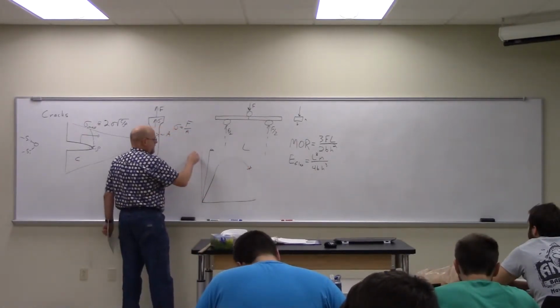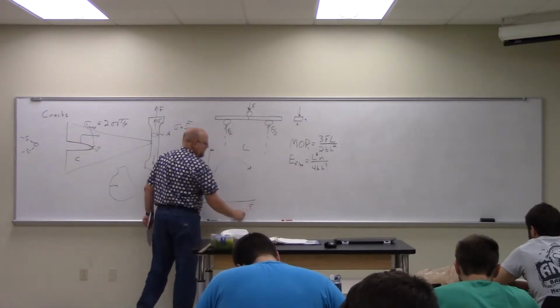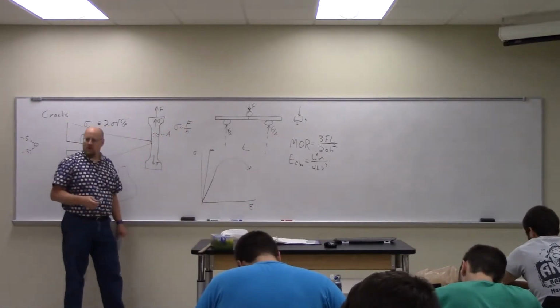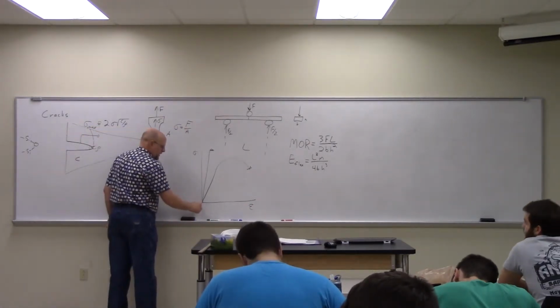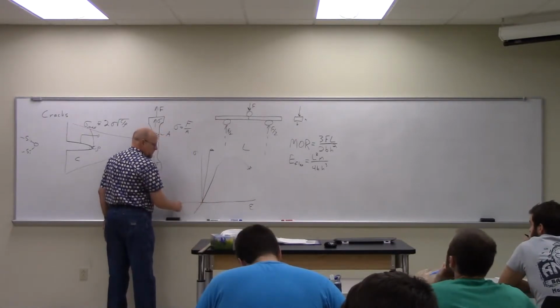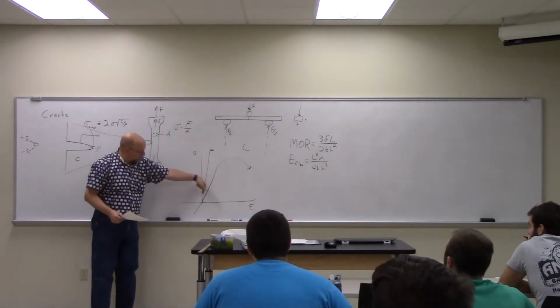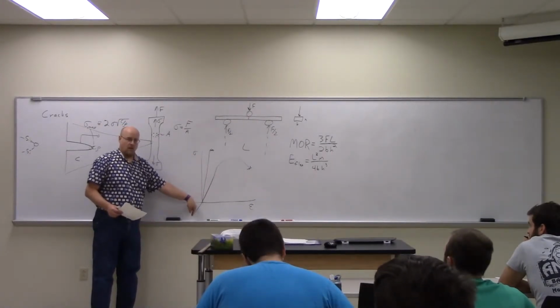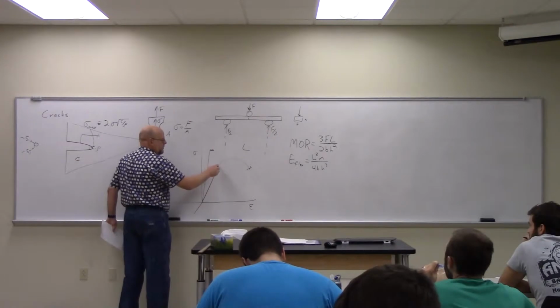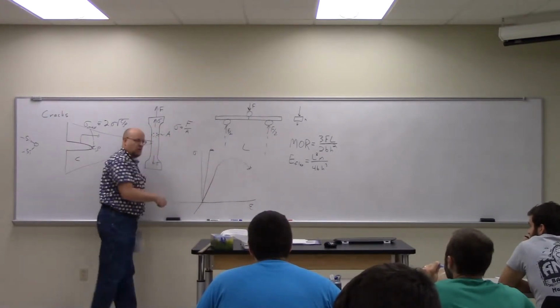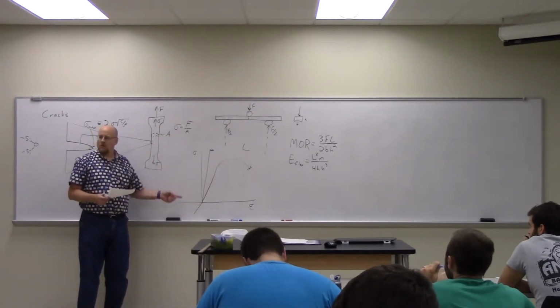It turns out that for most materials, metals and ceramics, if I went to a compressive stress, so I loaded it, in other words, I squeezed it instead of pulling on it, so I'm going down in a negative sigma, at least up to the point of yield, it would behave in a mirror fashion.